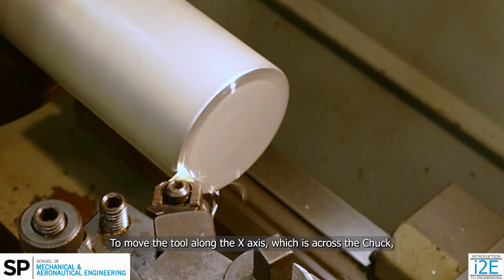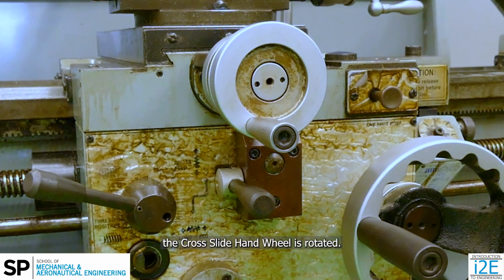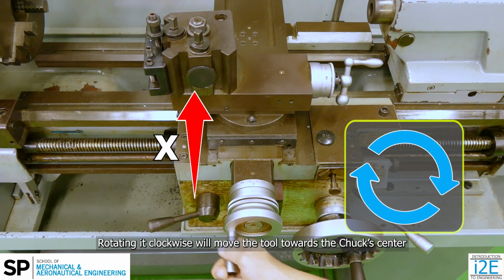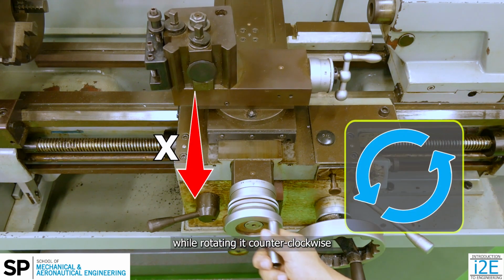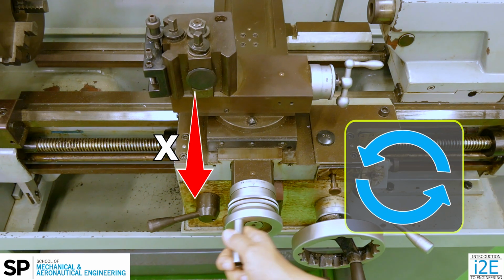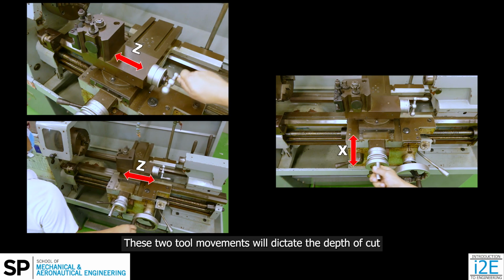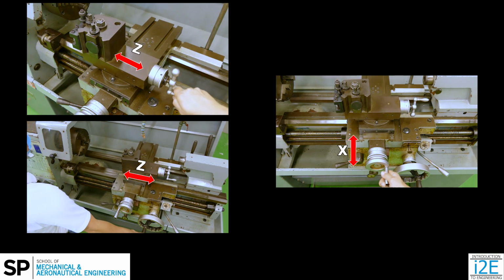To move the tool along the X-axis, which is across the chuck, the cross-slide handwheel is rotated. Rotating it clockwise will move the tool towards the chuck center, while rotating it counterclockwise will move the tool away from the chuck center. These two tool movements will dictate the depth of cut and feed direction for machining operations.